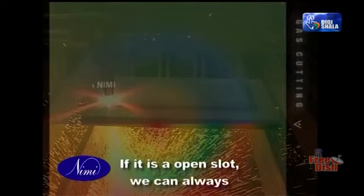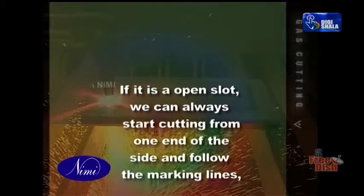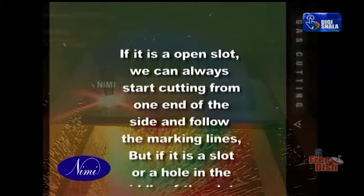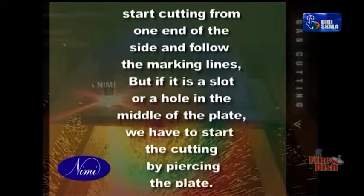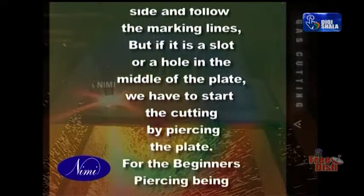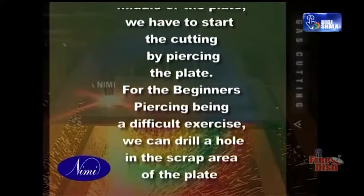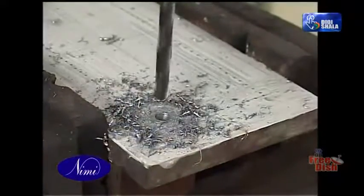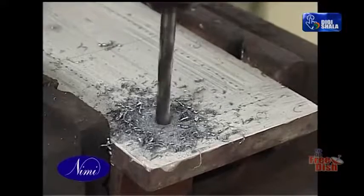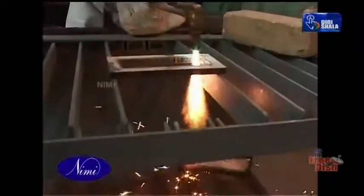If it is an open slot, we can always start cutting from one end of the plate and follow the marking. But if the slot or the hole is in the middle of the plate, we have to start cutting by piercing the plate. For beginners, piercing may be difficult. Hence, we can drill a hole in the scrap area at one end and proceed for cutting. Always set the job on the cutting table so that the parting piece is free to fall.